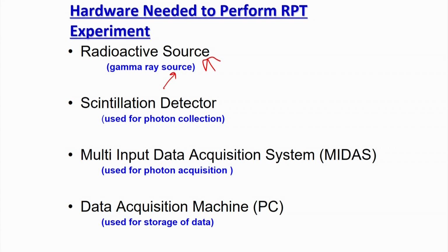In case of liquid tracking, the particle size should be smaller and the density should be equal to the density of the liquid. In case of gas tracking, I am sorry, that is the major disadvantage of this technique. You cannot track the gas by using the RPT technique, because it is very difficult to find a solid tracer particle which can match the density of any gas. It can do either the liquid tracking or the solid tracking.